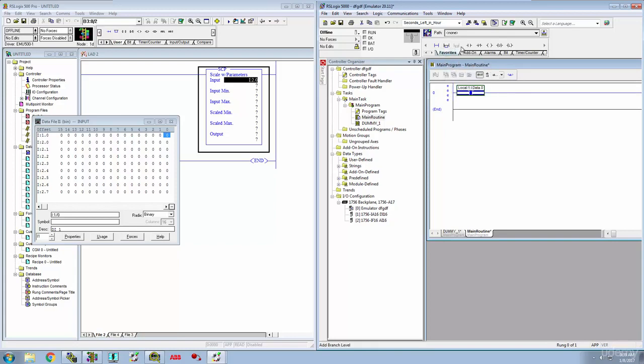Let's go ahead and create another XIC next to it, and we'll address this one to our DI_0. And you can see it pops that up below there and says, well, this is our Local:1, data on channel 0. So these two XICs, I addressed them a little bit differently.